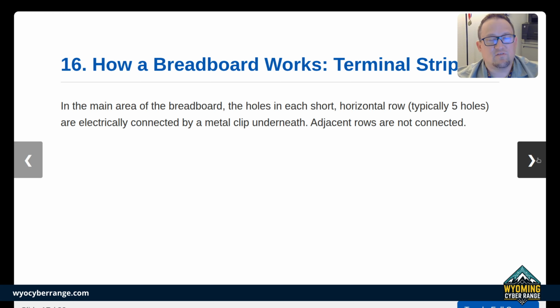And so you'll notice that those two lines are adjacent, and they are going to provide power all the way down the row. And so the way that the breadboards work is they will be connected horizontally. Definitely go look at that schematic at the end of the book so you can see exactly which ports on the breadboards are connected and which ones are not.